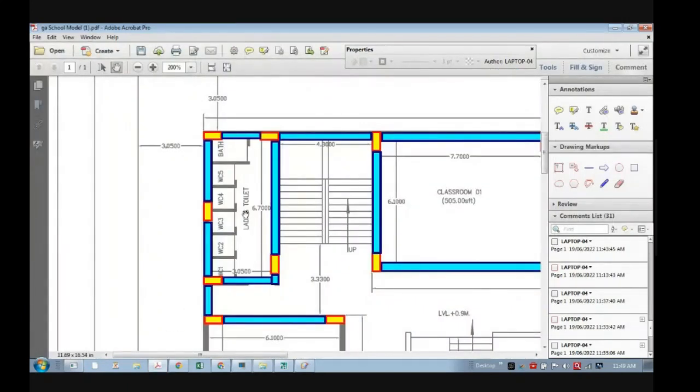Now what is ly by lx? Are there any two beams? That means how will my spanning be? And let's say, what is ly by lx for this? Ly means which dimension, longer or shorter? The longer direction, sir, in the y direction. So 6.7 divided by 3.05. Now tell me, will the value be less than 2 or more than 2? More than 2, sir. More than 2. Okay.